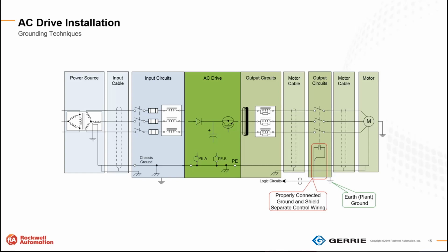Sometimes what we see is, let's say, the drive to disconnect termination is to one side of the box, and the disconnect to motor cable is terminated to the far side of the box, and we're relying on the box being part of that grounding conductor in there. We've had some issues with poor ground connections and EMI radiation from that, and some different things.